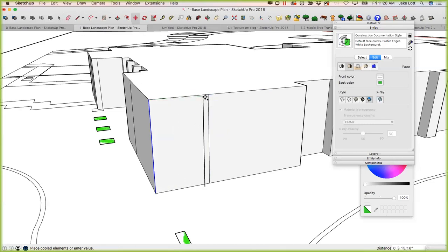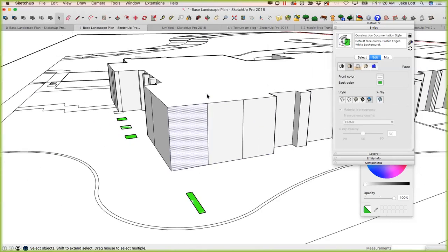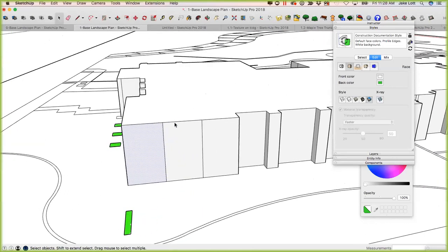So it makes it really easy then, as I'm drawing, as I hover over this line and I drag across, it tells me where those endpoints are, and I can go ahead and drop something in there, or again, use the move tool, select a line, click a starting point, and hit your Control or Alt, and be able to make a copy of that line.